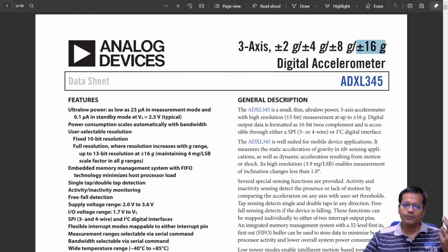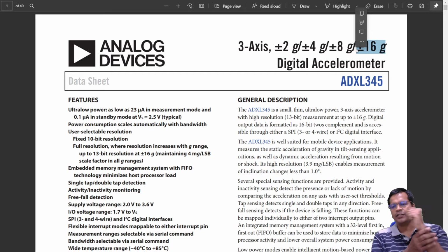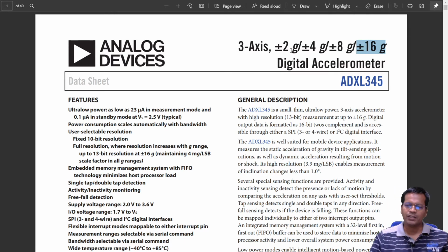If you are using just an accelerometer fitted in your sports watch, this should be quite good enough. But if it is in a collision detector, even 16g may be less. So you can put your accelerometer to different configurations. One of them is always active, and once that configuration is set, it starts working.